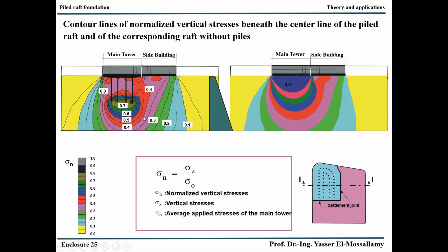We transfer the stresses to deeper depths where we have higher E modulus of the soil, and hence this is the reason why we can control the settlements very effectively by applying a fewer number of piles in case of wide raft foundation.